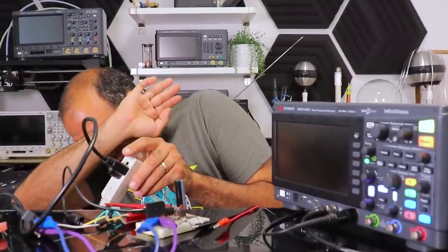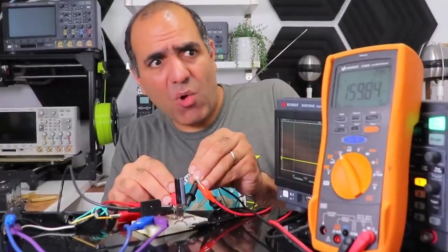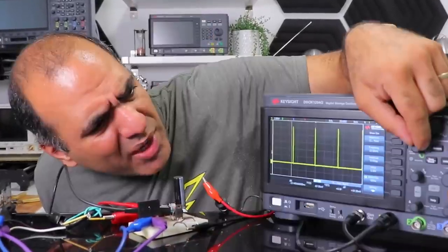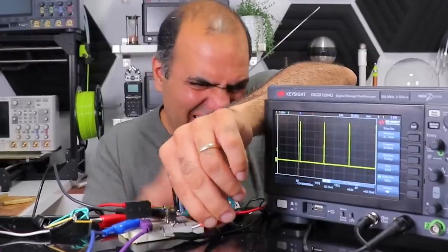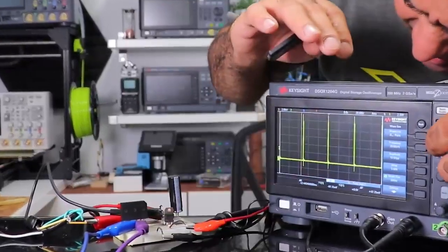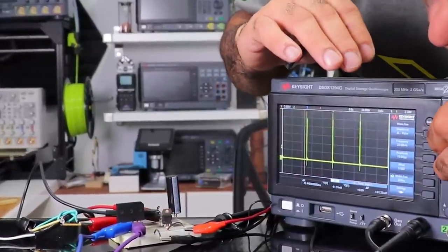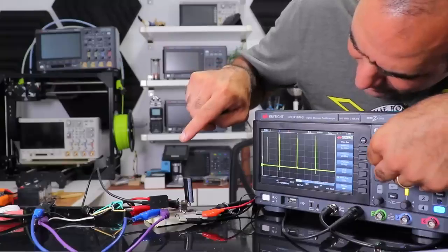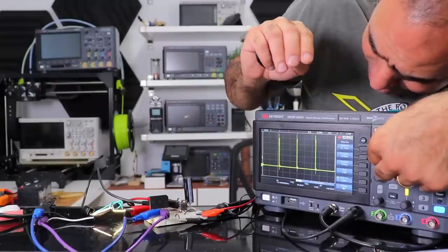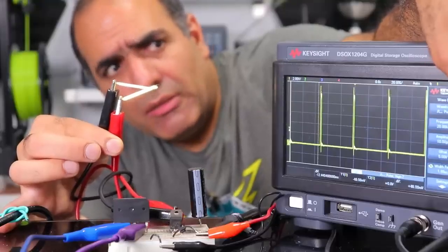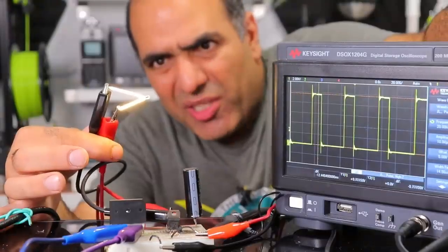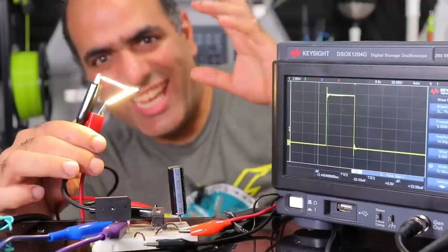Please don't blow. We have what? 160 volt DC? 20K signal confirmed at very low on time. Connecting the signal. Very slowly increasing the duty cycle. Oh, I can see the LEDs blinking. I'm doing it! I'm doing it! God, I'm sweating like a pig here. It's getting brighter. Let me lower the frequency. It works.